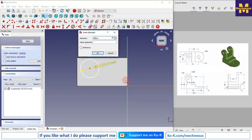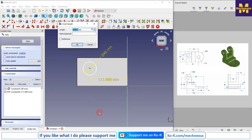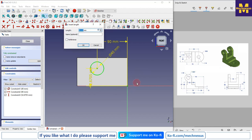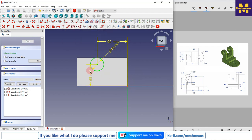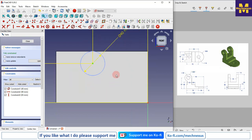diameter 40, and from this edge it is 90, and vertical it is 65. So I will select this point and this point and give the 65. Okay, so we do not require this circle as a part of our extrusion, so it will be a construction. So I will make it a construction.